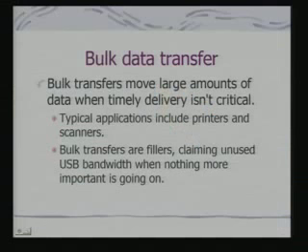In many cases, bulk transfers become fillers, claiming unused USB bandwidth when nothing more important is going on. Since there is no deadline to satisfy, it is not essential that the USB bus has to make a guaranteed bandwidth available to this transfer type. So it can be put in whenever there is a gap, but large volume of data is to be transferred. This is the basic aim.